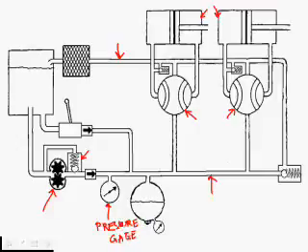And it's very typical for the pressure gauge to be mounted in the pressure line right downstream of the pump. So it's telling you the pressure of the fluid that's being supplied to the selector valves and the actuators.